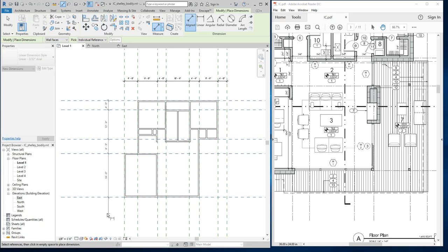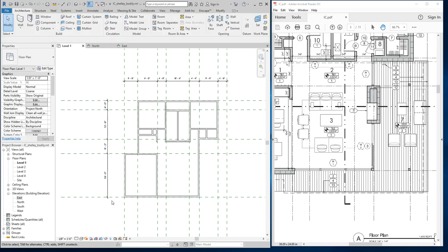Click, and then I just click over here, click, and because it didn't have an element to sense, it just ended itself, essentially. So I could leave those dimensions there just to give me a visual cue on, hey, were my grids right? Did everything lay right? Of course, I'm putting dimensions all over the place in here to place things. You'll notice that when I place something, if there's a dimension associated with it, I finish my work and then I delete the dimension, right? Because I've learned over time that you get a lot of elements in these drawings, and the cleaner they are, the easier it is to work. So you're like, well, why didn't you just leave that dimension so you knew it was right? Well, I just know that if I leave 50 dimensions all over the place, it's just going to get messy. So I delete them.